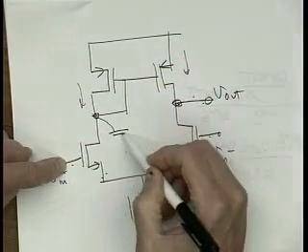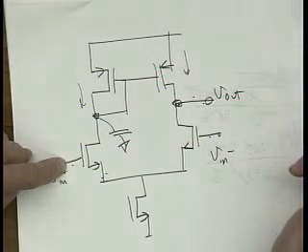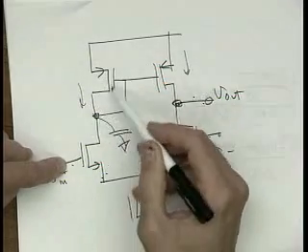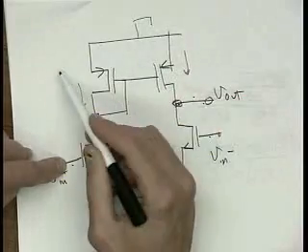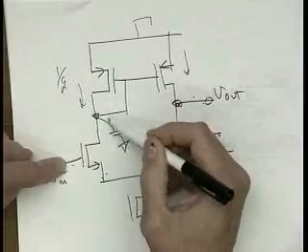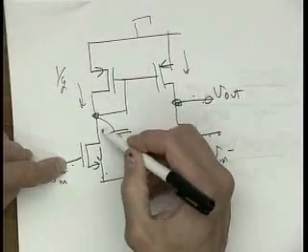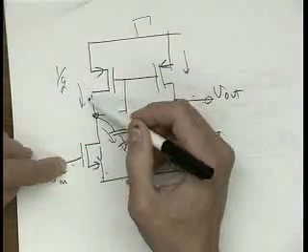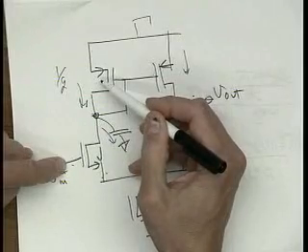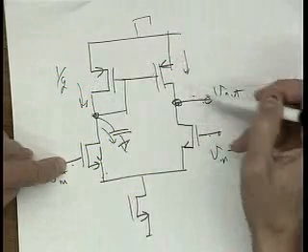So what do we have to worry about? There's capacitance on this node on this side. So you're going to begin to see this, and the time constant here is relatively 1 over gm for this resistor right here. With this kind of current division, effectively some of this current is going to start going into the capacitor instead of going into this transistor right here. And effectively we'll have less current being mirrored over here coming to our output.